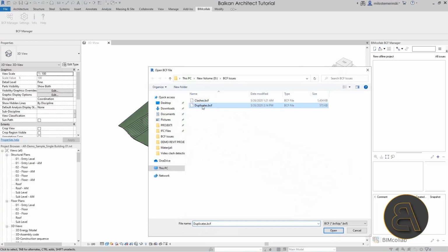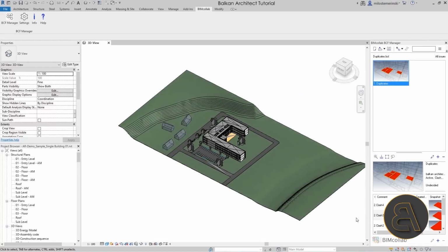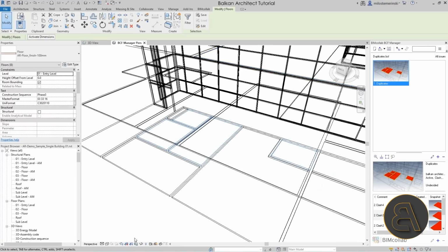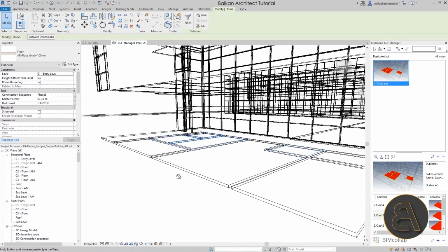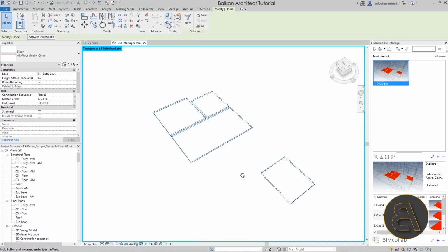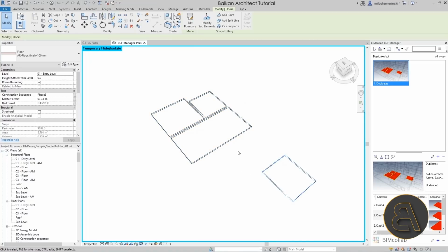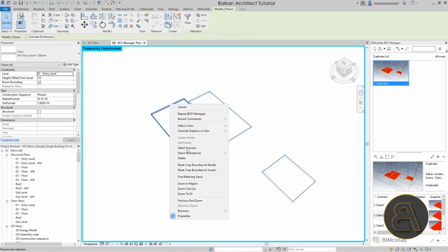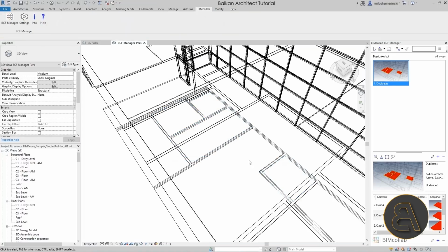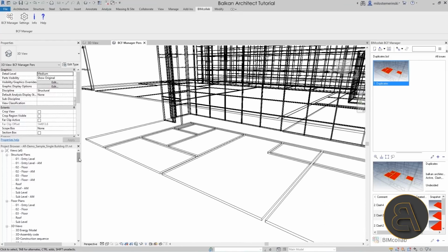It's fairly straightforward to install this plugin, and it can open up that issue that was issued by the project manager. And as soon as we click on that issue, as you can see here, it shows in Revit exactly where that issue is, and we can isolate all of the elements, and we can just delete all of the elements that we no longer need because, well, they're overlapping, they're duplicates.